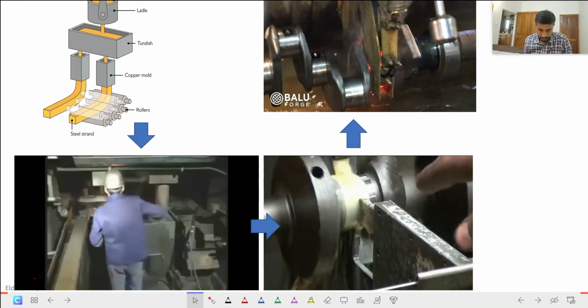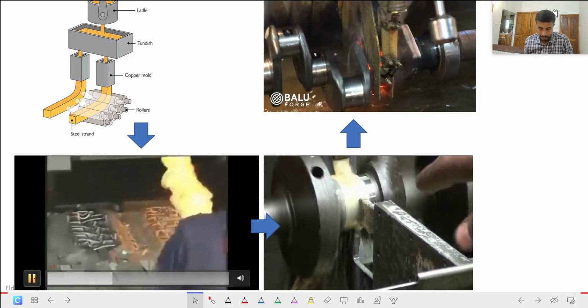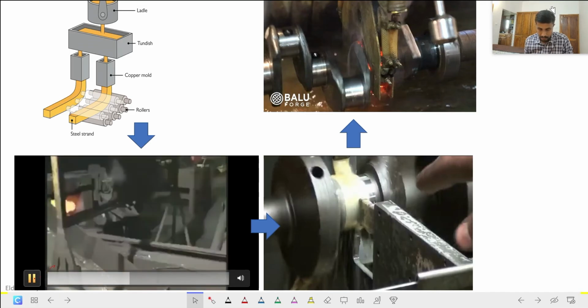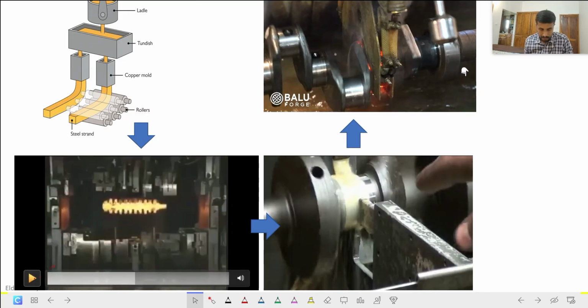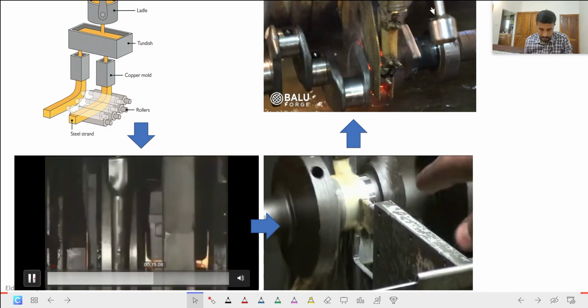The pre and finish forging of a 5-cylinder crankshaft is performed in plain dies. See, this press has a particular cavity here, and when we press in between the dies of the press, the billet changes to the corresponding shape. Afterwards, the workpiece is clipped. The flash goes to the scrap bin, while the crankshaft is transported to the next station. At the end of the pressing operations, we get an approximate shape, or near net shape, of the crankshaft. Then a twister is an operation in which the 5 strokes of the shaft are properly aligned relative to one another by twisting.